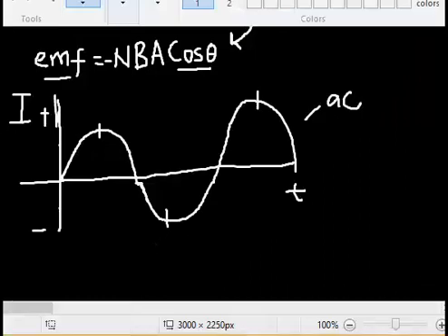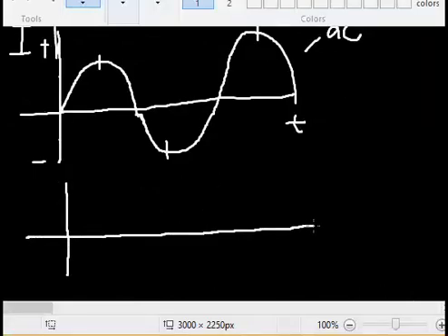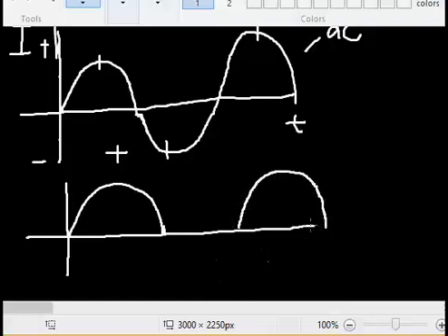Now, what happened here? If that conversion has succeeded, what you have is a wave that only has the positive part. This split ring cuts out the negative part of the wave, so the wave will not have a negative part, but a positive cycle throughout each period. So please take note of that. That is the AC generator.